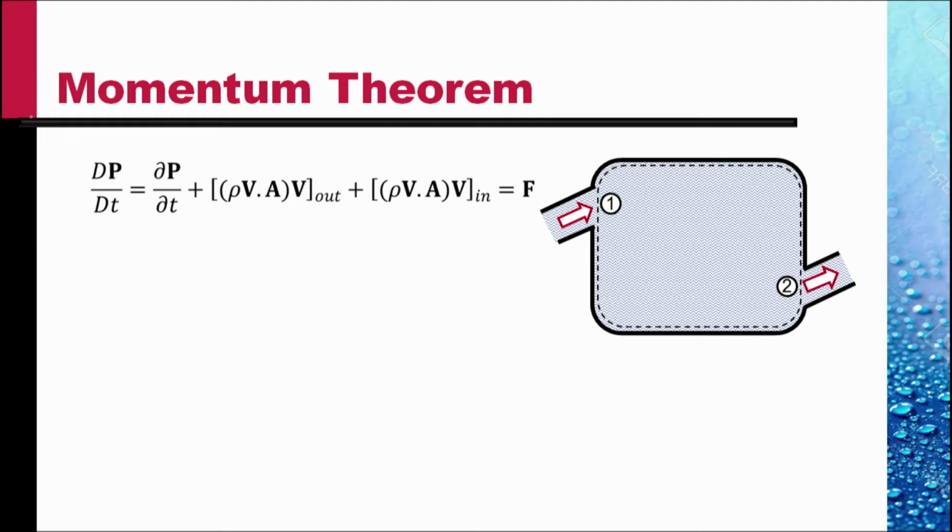Since the area vector A of a surface is pointing outwards, V dot A positive would imply an outflux. V dot A negative would imply that the velocity is opposed to the area, and the area is taken positive outwards, so V dot A negative means it is an influx.